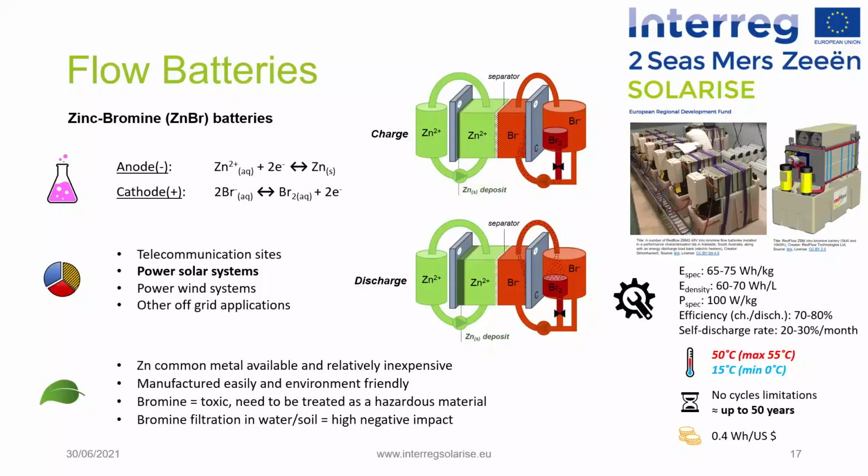Among this type of battery, we present here the zinc-bromine flow battery, where a zinc bromide solution is stored in two tanks. When the battery is charged or discharged, the solution or electrolytes are pumped through a reactor stack and back into the tanks. One tank is used to store the electrolyte for the positive electrode reactions and the other for the negative one. During charging, metallic zinc is plated from the electrolyte solution onto the negative electrode surfaces in the cell batteries. The bromide is converted to bromine at the positive electrode surface and is stored in a safe, chemically complex organic phase in the electrolyte reservoir.